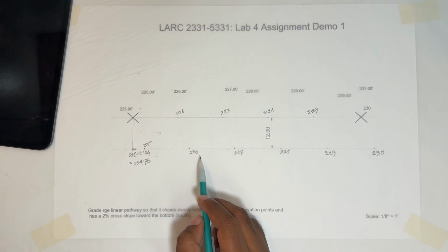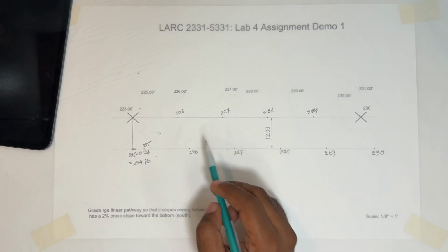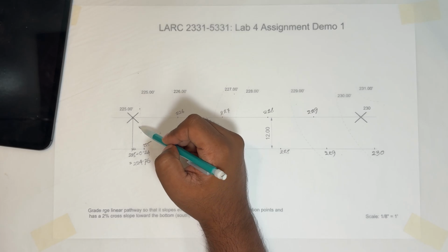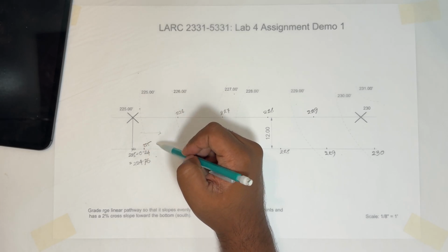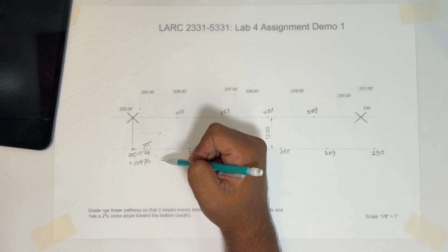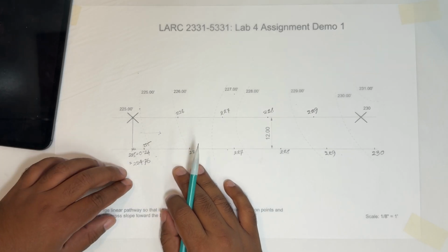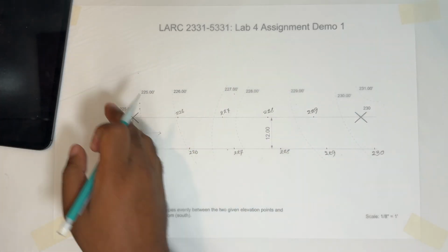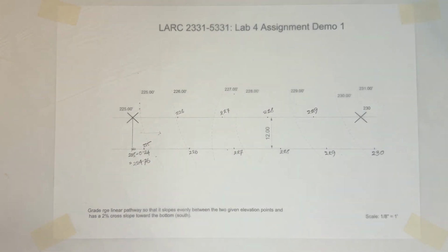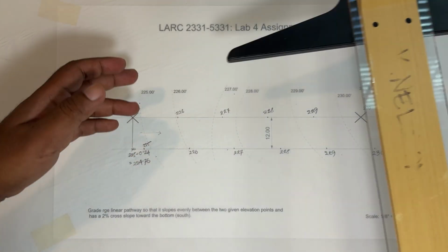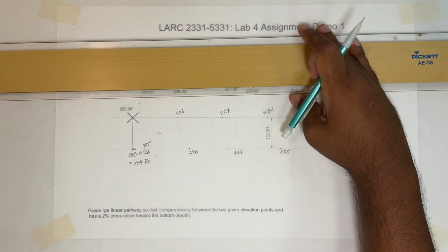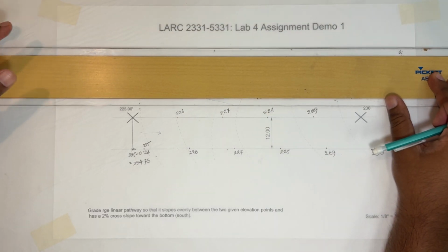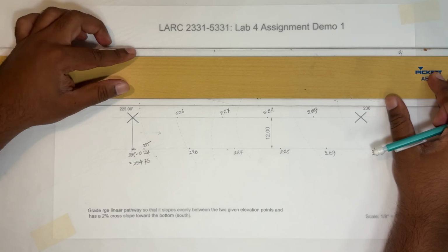Now that we have calculated the elevation points for both the upper portion and lower portion of the road, the contour lines need to have a smooth transition between the existing and the newly drawn contour lines. So I will do just that. I will create somewhat of a distance between the actual road and the point we will start to create the grading from, and we will learn more about this in the near future.